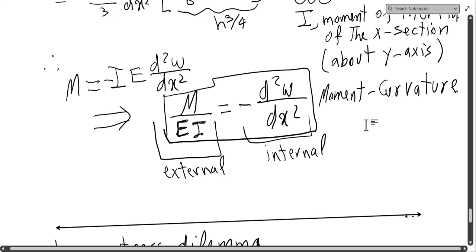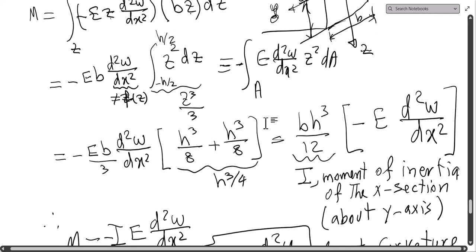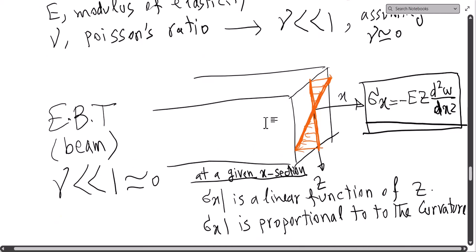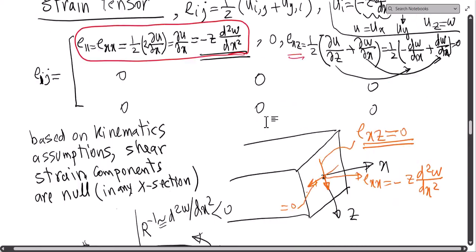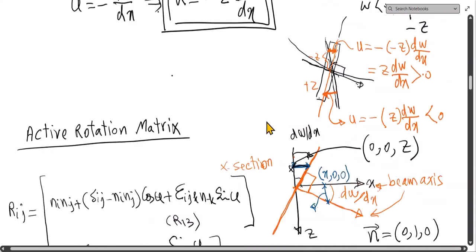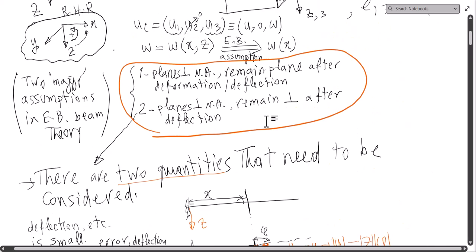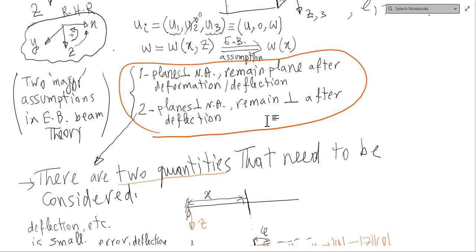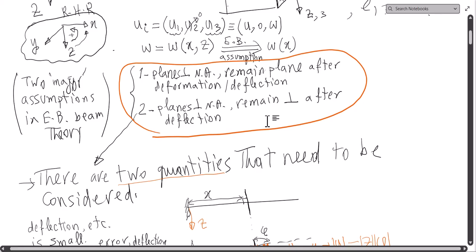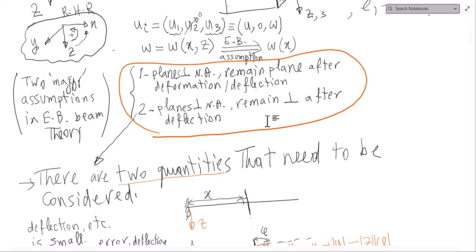The assumption is valid when our length is much larger than a cross-sectional dimension. We usually have a length of maybe 6, 7 meters, or on the order of meters, and the cross section is on the order of millimeters or centimeters. As long as the ratio of length over typical cross-section dimension is above 20, we are safe to make the assumptions that we make.